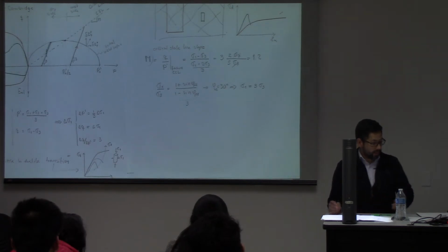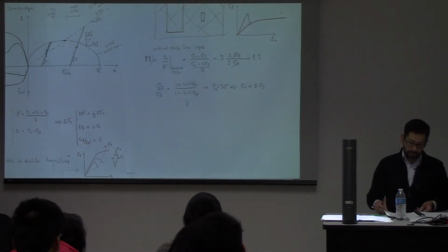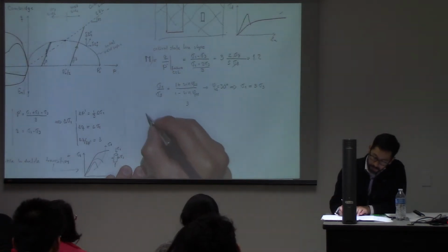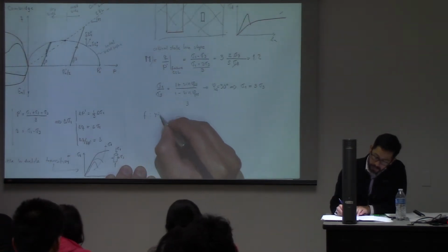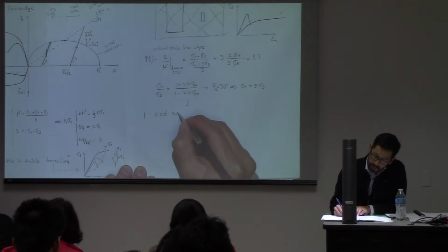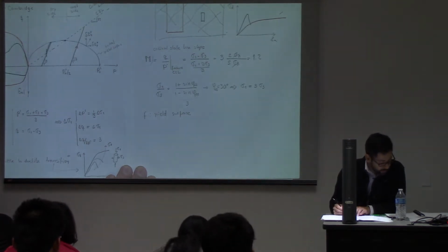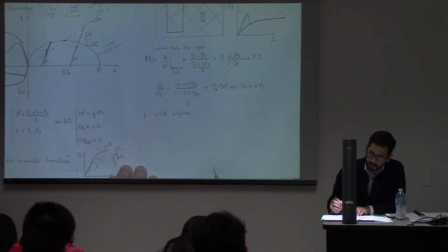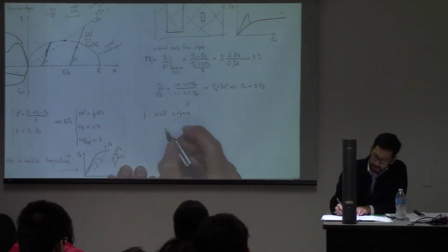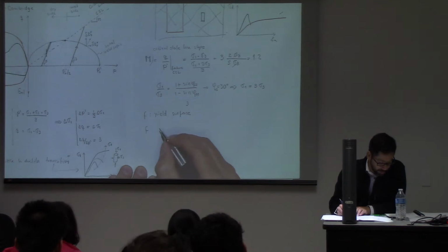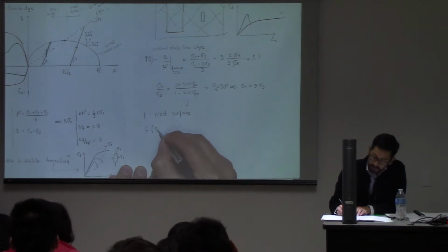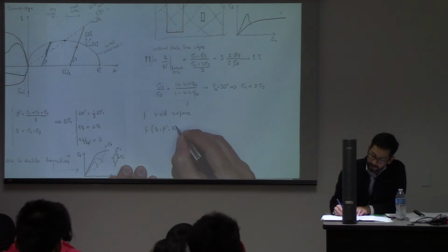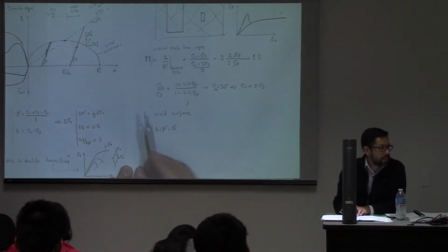What about that ellipse? What is that function going to be? That's going to be F, and it's a yield surface. And we're not going to develop it from scratch, but I'm just going to tell you what that function is. It's a function of Q, it's a function of P prime, and it's a function of P0 prime. Right?